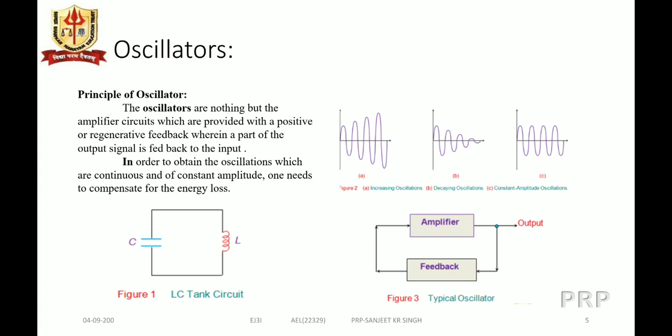So at that moment, as the polarity is reversed, the lower end becomes positive and the upper one becomes negative for the inductor L, so that it makes the current continue in the LC tank circuit, as the inductor has the property of opposing any change of current.